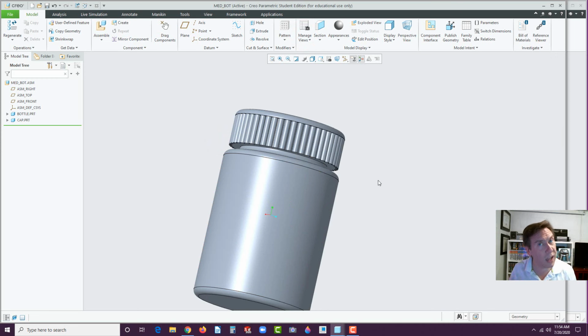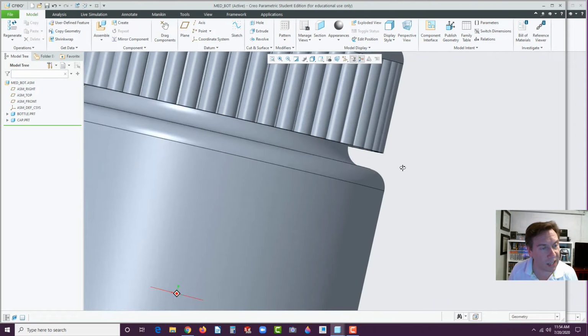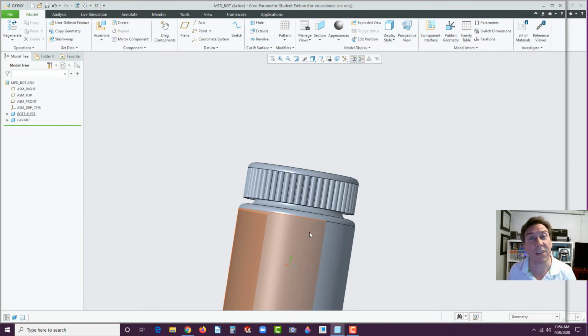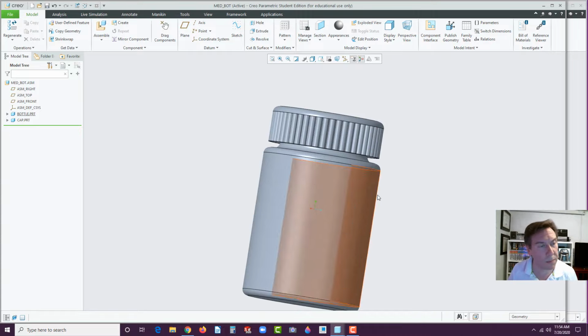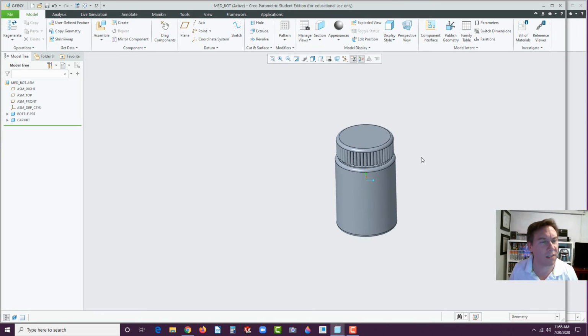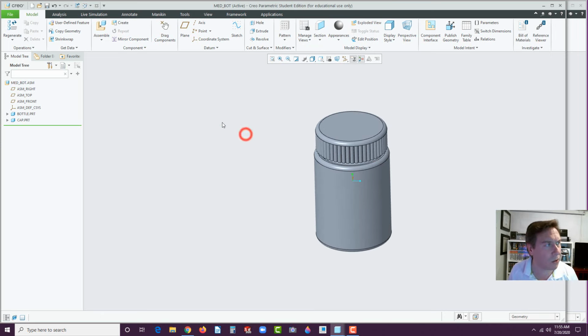Now, if you do it any other way, you might run into problems. I've had students collapse if they select this face to this face right here, and then there's an interference, 20 points off. So just be aware. Okay, now we could explode it, but there is actually an auto explode already in there, and if it's aligned correctly, as long as you got both of those relationships, it will align itself directly above it in the auto explode. So you don't even have to explode it if you didn't want to. I wouldn't even recommend it, actually. It's going to explode later when we bring it up into the drawing.